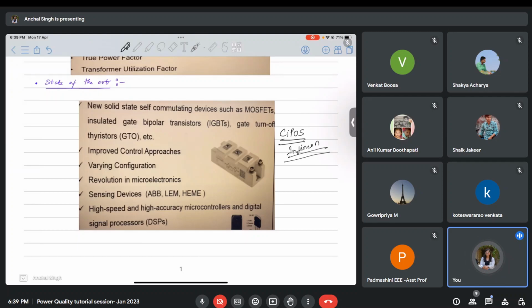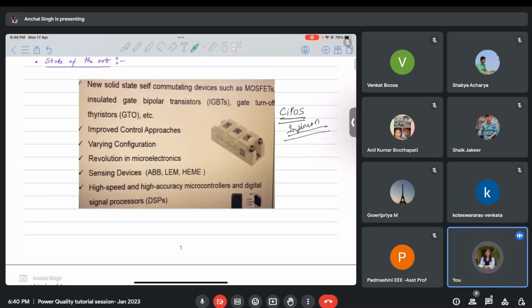So this IC looks like something like a miracle, right? Initially, when you have to turn on a switch, you have to design the gate driver circuit. Then to the gate driver circuit you give PWM pulses. But all of that has just come in one simple small IC. It's a very small IC. It's a bit costly, but it's very small. In that IC, there are 6 switches present, so you can make a 3-leg converter from one IC. You just have to give the PWM pulses to that IC, and it will do the switching. So this is the advantage of advancement in microelectronics.